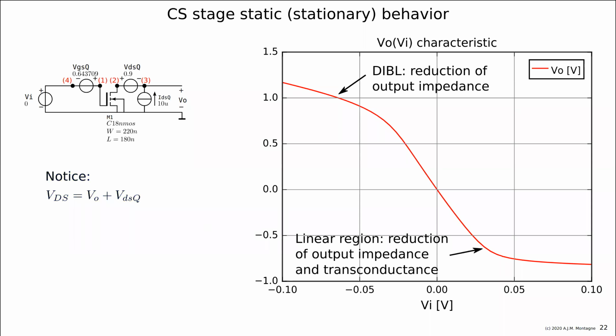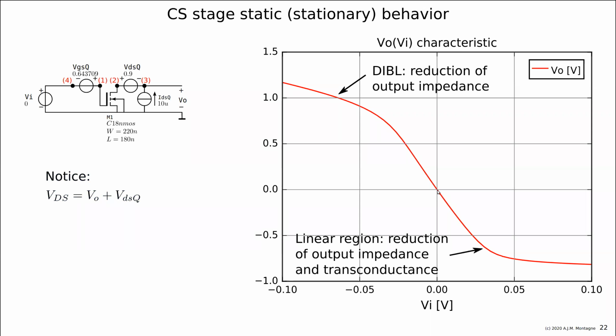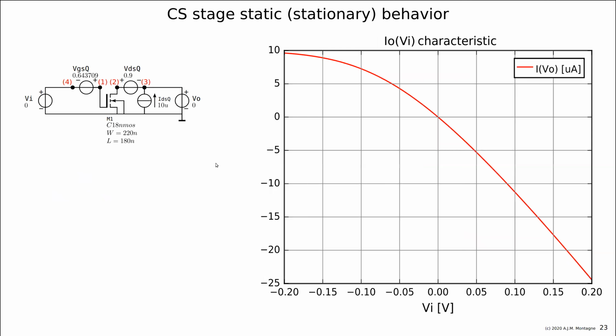Now let's look at the next curve. The next curve is the short circuit current, so voltage to short circuit, and you see, oh, that's what I forgot to say, but here it's clear that it goes to the origin. 0, 0. And here also, this is what we expected because we designed the biasing as such, and this one is capable of sourcing 10 microamps and sinking much more. That depends, of course, on the device geometry of this transistor, because it's like 0.9 volt divided by RDS on of the device, and that depends on what your drive voltage will be.